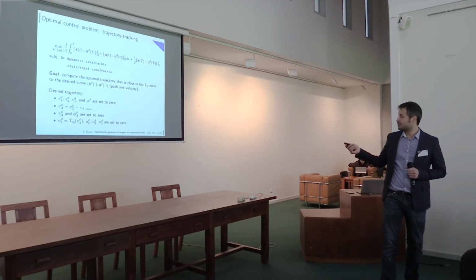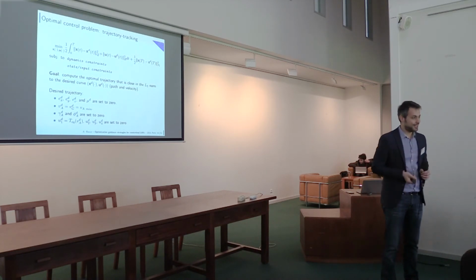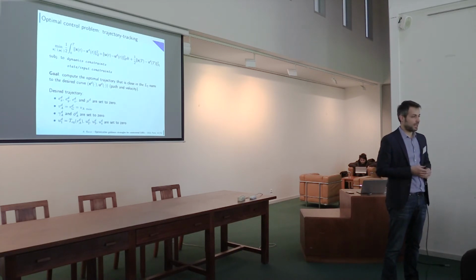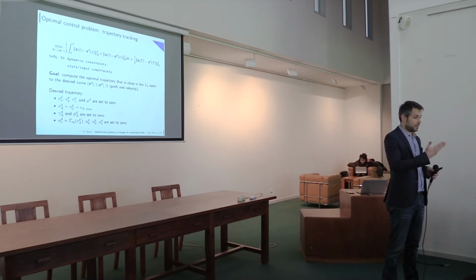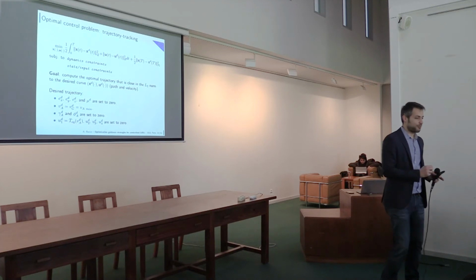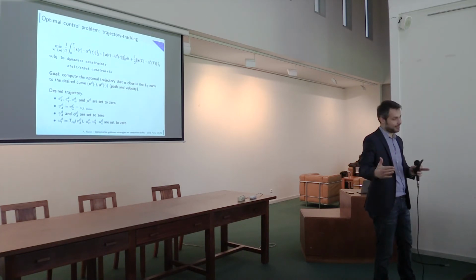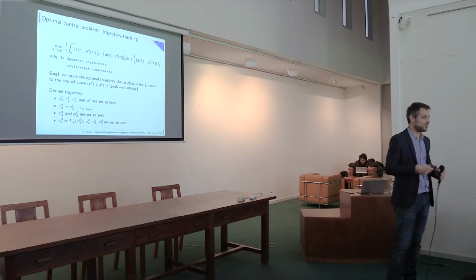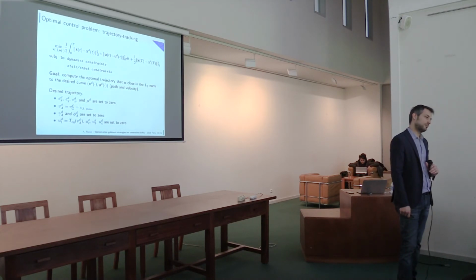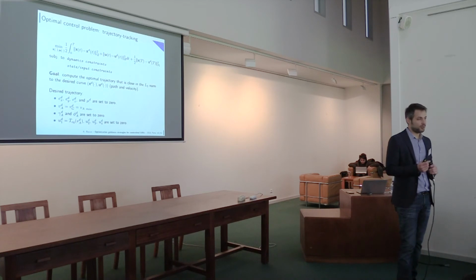What you can do is compute this P1. It's not something that we tune, but we compute P1 by solving an algebraic Riccati equation that gives you some properties and stabilizes everything. So some nice properties over there. If you have the case of a loiter maneuver, where you have a curved path in the middle of the maneuver, we can always add a final path, which is a straight line or a loiter maneuver that has some nice properties. We compute this matrix. I was more talking about a curved path. Yeah, we can do it. In that case, you have to tune that P1 matrix in an appropriate way.